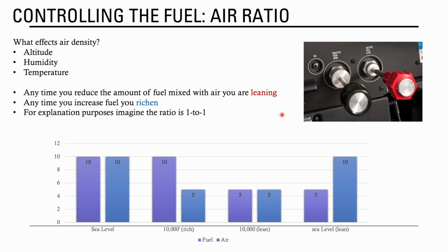Does the mixture level stick click as you're pulling it out, click, click, click? No, it's one smooth trend all the way. If you push the button, it's smooth. You can do major changes or really small ones, or if you spin it, you can get pretty small increments because it's threaded. So it's all based on touch and feel of the plane. If you're just climbing up slowly and you need to make really minor changes, you can bring it out slowly, do a couple twists, leave it, do a couple twists, leave it.